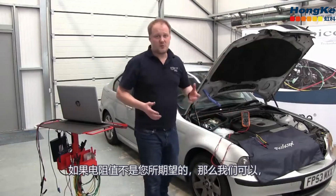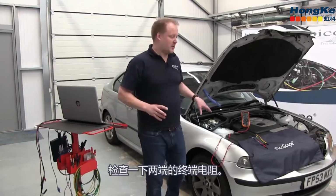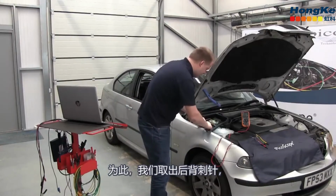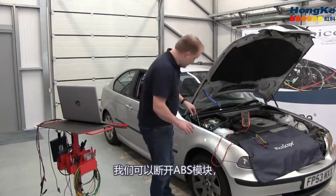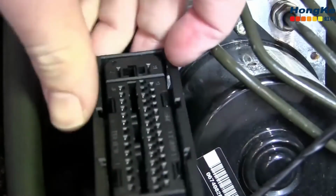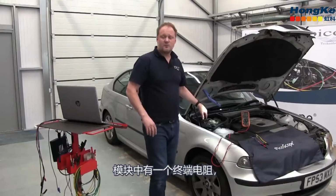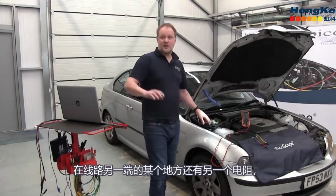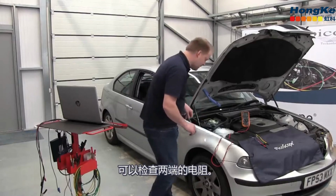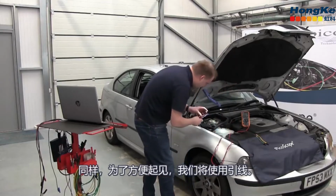Say it wasn't good, what you weren't expecting, then next thing we could look at is the termination resistors at each end. So to do that, if we take out the back-pinning probes, we can disconnect the ABS module, and there we go. Knowing that we've got 1 termination resistor in the module and another resistor at the other end of the line somewhere, we're well placed to check for the resistances at the 2 ends.